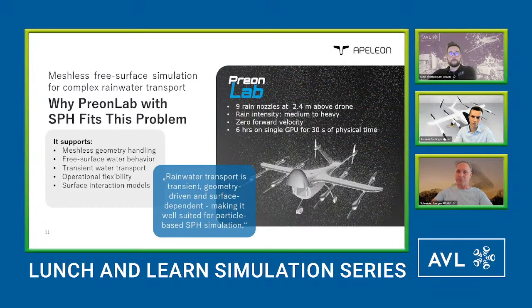We of course now want also to share a little bit about what tool was used and what kind of methodology. So we're using here PreonLab, which is an SPH based approach. So it's CFD-like, but the big advantage is you don't have to care about meshing. So you can directly load your CAD data in.